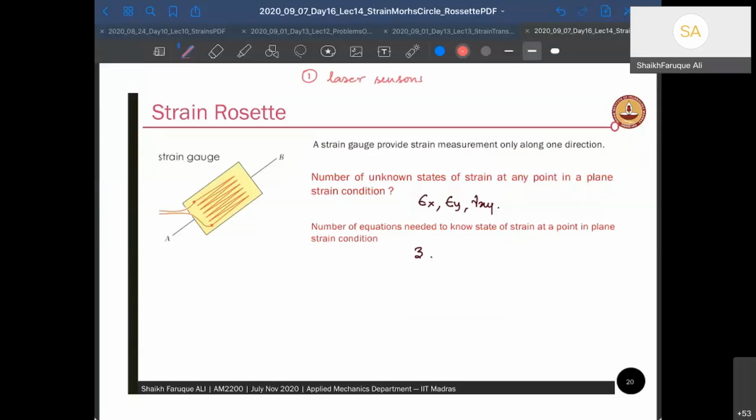What it does is, let's say I have a beam here, and you point a laser to some point here, let's say some point there. I am putting a laser here. Okay, so when it deforms, let's say it deforms in the other direction, this laser will calculate how much it has deformed based on the change in the position P. So this might be your 0, and then you can calculate this. So the laser sensor gives you how much deformation it has.